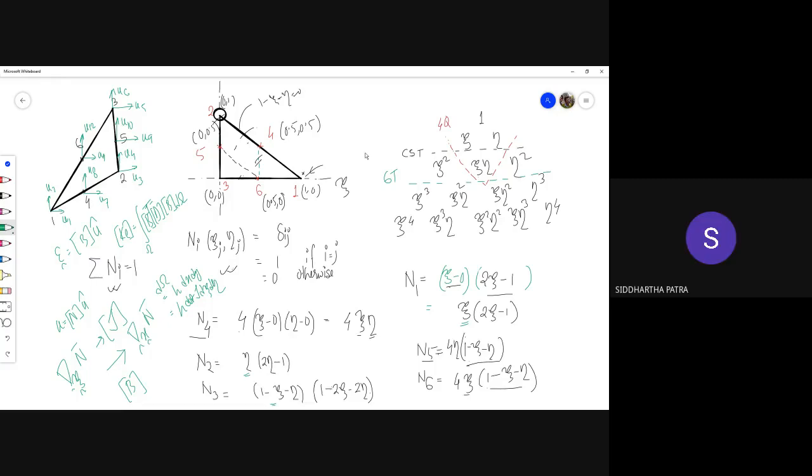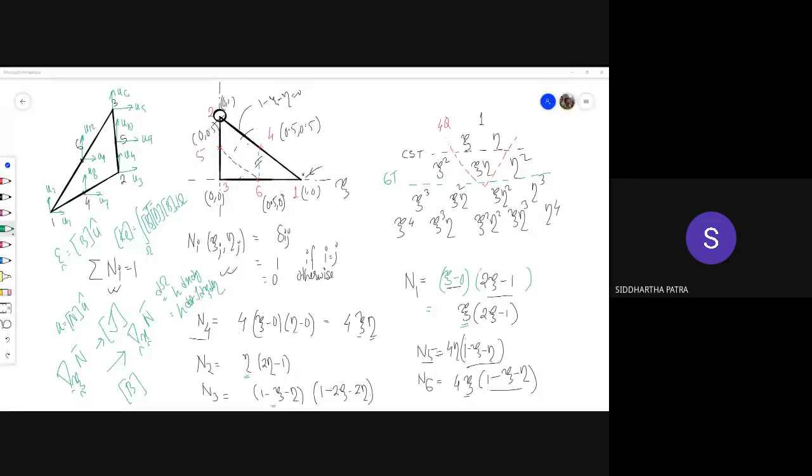Although the shape functions were different, for CST those were linear shape functions, and for the four-noded quad element they were bilinear shape functions. But once you move to a given side, then either xi or eta is zero, and the shape function becomes linear in the other coordinate.